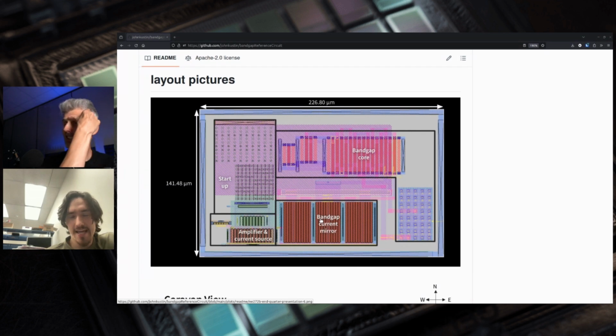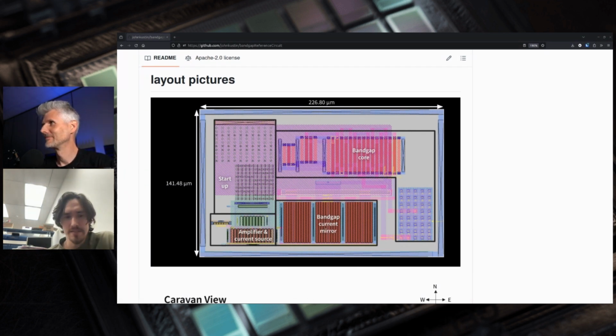Yeah, exactly. I think this comes from some PCB experience. Let's say in my case, there's a particular chip that I want to test, and that is in the very center. The most important thing is in the center, and maybe applying that lesson to this layout, I would put the BJTs in the center and then work out from it to ensure that across any kind of gradient, like from lower left to top right, or any direction that the processing, the etching might happen in, there's symmetry. There's something called a common centroid, and it's good to know what that is, but I think I wouldn't go for that style. I would just put the active BJTs in the center and then work out from there.